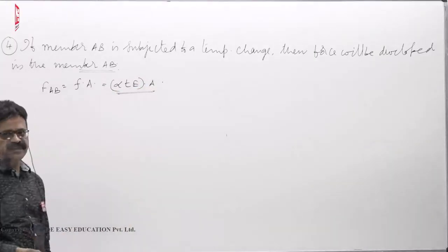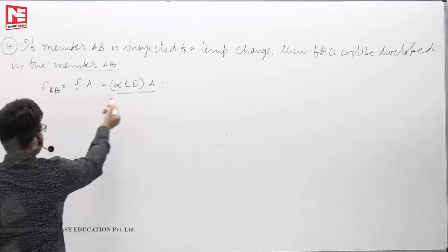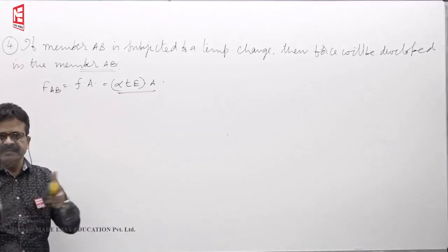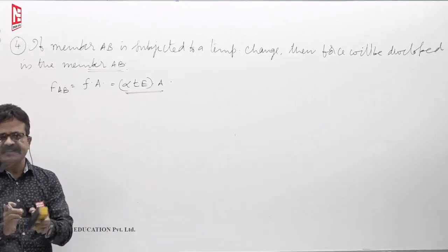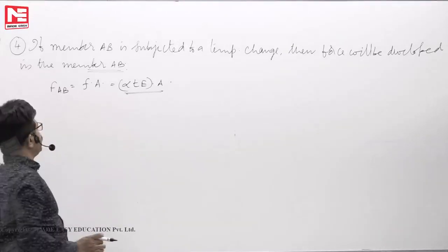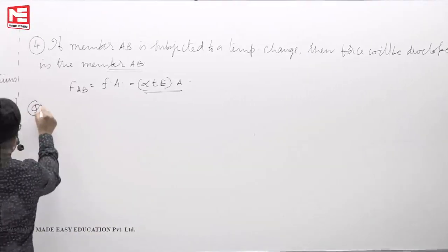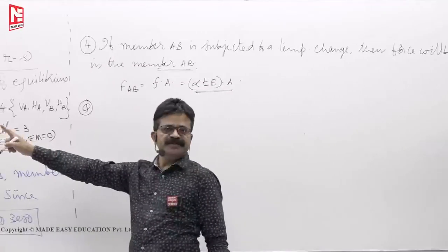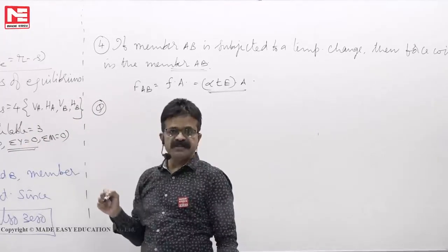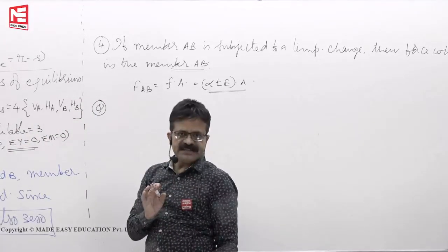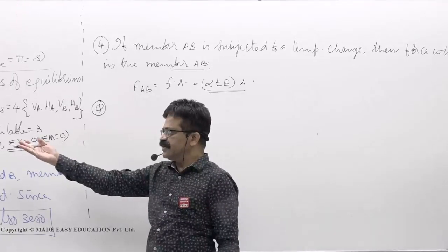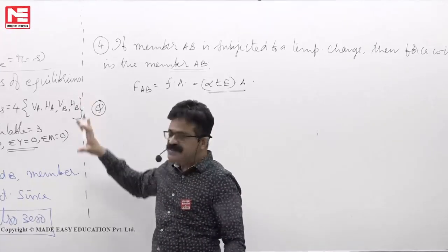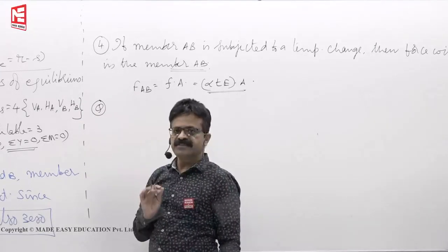Now this becomes like a strength of materials problem. Force in member AB is so much. It can be tensile or compressive: if you are heating it, then compressive stress. If temperature decreases, then tensile stress will develop in the member AB. Okay. How a numerical question can come is like this. In this case, by inspection itself F_AB is 0, but once they have given you 2 marks, it will be over in 10-15 seconds. Just detect that it cannot elongate or contract, it is 0. Solution is over. Now I am discussing the structural behavior of such trusses.